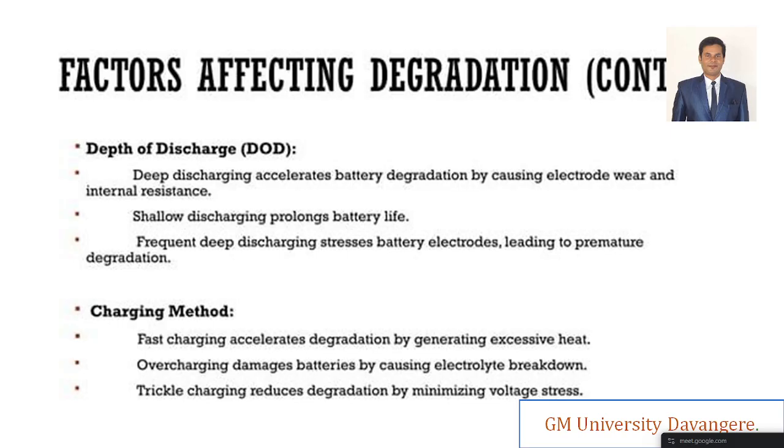And also, if we talk about the various types of charging methods, right? The state of charge, the state of health, the depth of discharge, right? The depth of discharge accelerates the battery degradation by causing electrode wear and internal resistance, right? So there is a chance of wear and tear in the batteries sometimes. So the depth of discharge would also be a reason for degradation. It makes the degradation faster and faster, reducing its lifespan as much as possible, right? Shallow discharging prolongs the battery life.